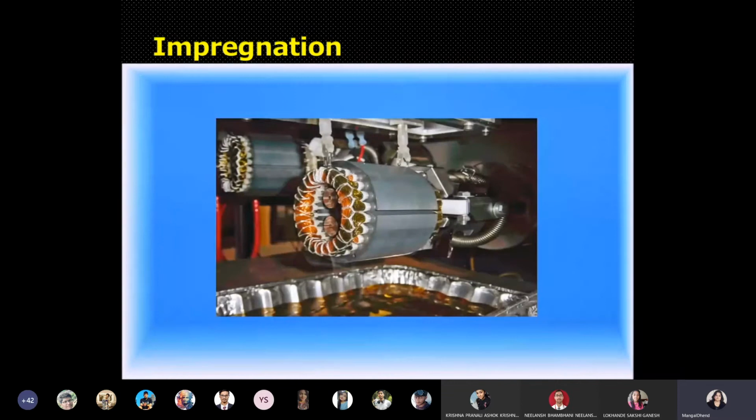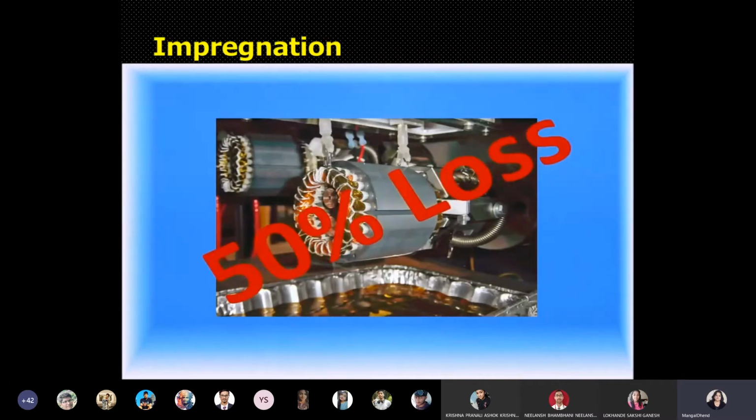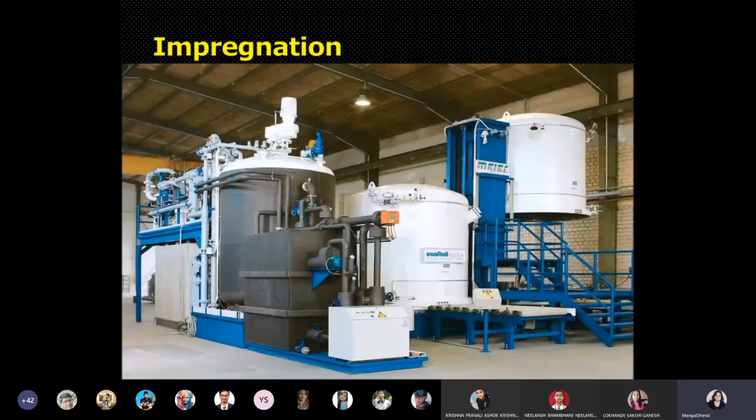Even for low-voltage application, VPI is greatly superior to solvent-based varnishes and the conventional dip-and-bake method. Varnishes tend to lose about 50% of the initial volume during baking, leaving voids and air pockets in the windings. However, due to VPI's use of resin under a vacuum instead of varnish, it provides a nearly 100% solid structure, guaranteeing the leak-proof and corrosion-proof requirements of parts and components in critical operations. VPI can be used for AC and DC stators, armatures, and field coils.